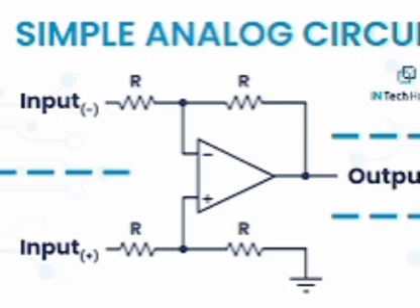Current gain of CB is less than unity. Current gain of CE is 100. Current gain of CC is 100. Voltage gain of CB is 150. Voltage gain of CE is 500. Voltage gain of CC is less than unity. Leakage current of CB is very small. Leakage current of CE is very large. Leakage current of CC is very large.